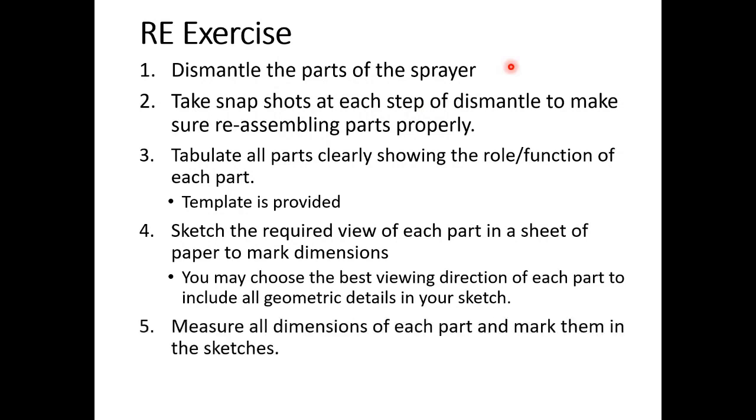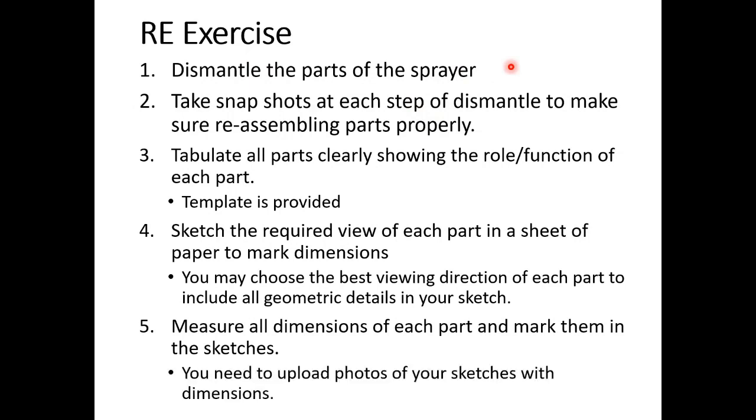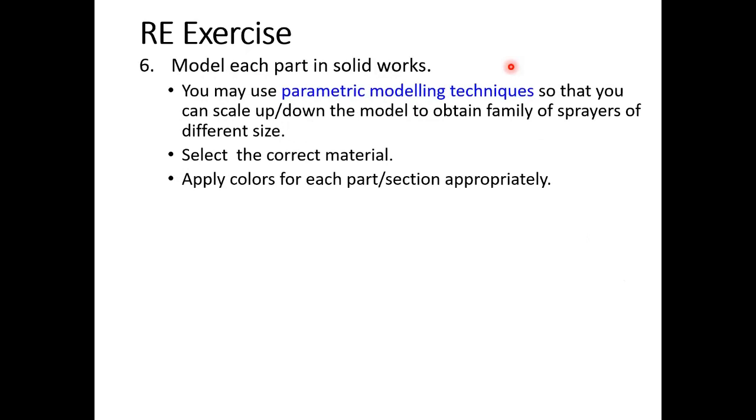And then we'll give you some measuring equipment. So you could measure each dimension of the part using those instruments, and mark these dimensions on your sketches. And then using SolidWorks, you could model each and every part. And I strongly advise you to use parametric modeling techniques, because as a part of this exercise, we are trying to obtain several versions of this product. Parametric modeling techniques will help you to do this resizing of components very quickly rather than remodeling right from the beginning.